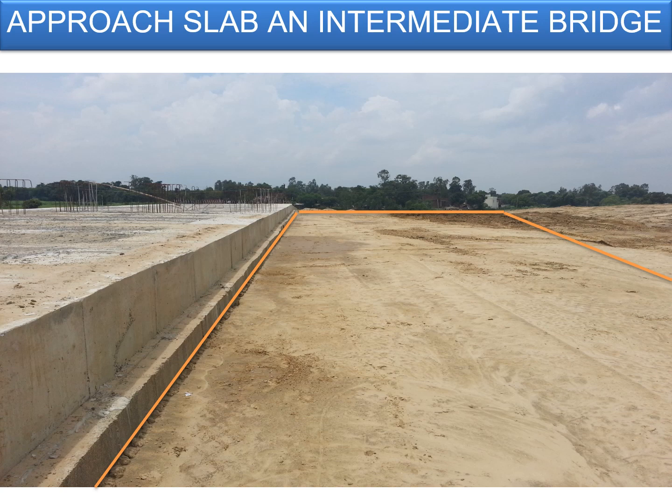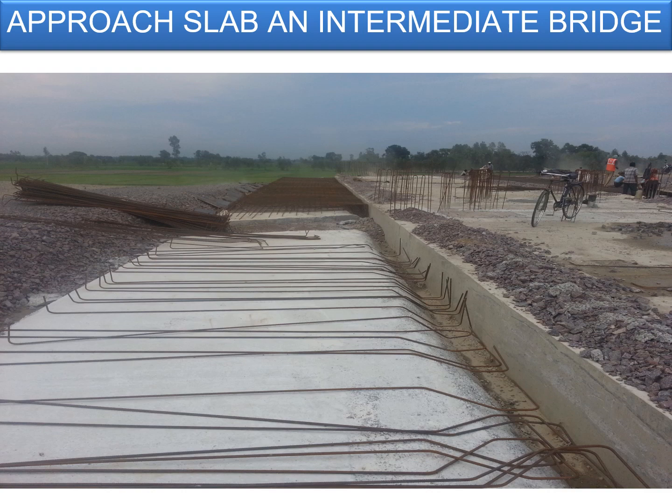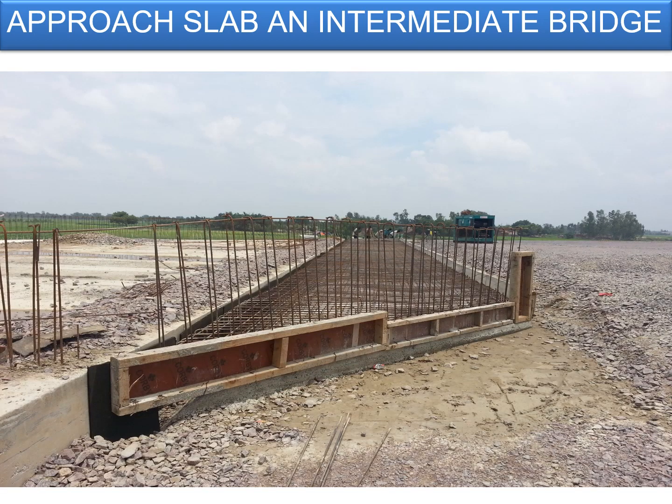Then to construct the approach slab, you need to have a PCC on the gap between the bridge face, the back of the abutment wall or the back wall, and the existing road. And then this will be covered with an RCC slab of say 300 millimeters thick, and maybe around 3 meters or 3.5 meters in length along the line of cross section of the road pavement.